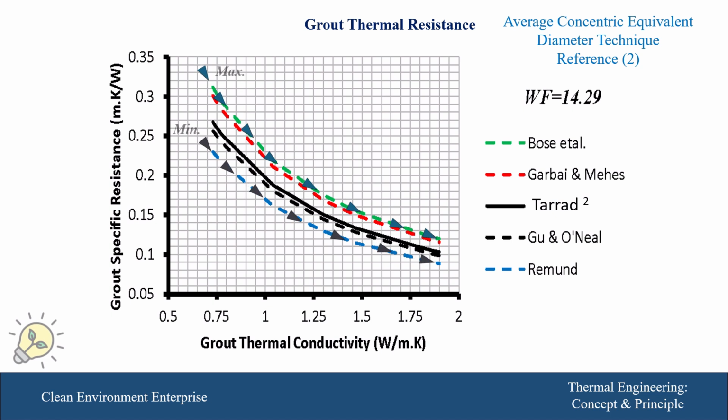But again, our focus should go in the direction of selecting a proper equation, and all of these correlations predicted the same trend for the grout thermal resistance: as the thermal conductivity of the grout increases, the thermal resistance will be lower.